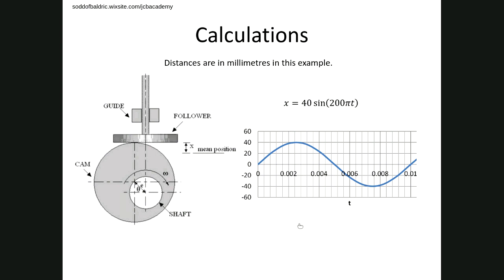Okay, now the first thing you guys are asked to do is work out what the periodic time is. Now if you look at this, the periodic time I'm showing you on a graph here just to help the explanation. It's the time taken to go from one point of the graph to the same point of the graph, because this then repeats itself, and that's why I've left a little bit of the trace on to show that it carries on. It just repeats itself. It's what we call a periodic waveform. The time taken to do one period, you can see from this graph, is 0.01 seconds.